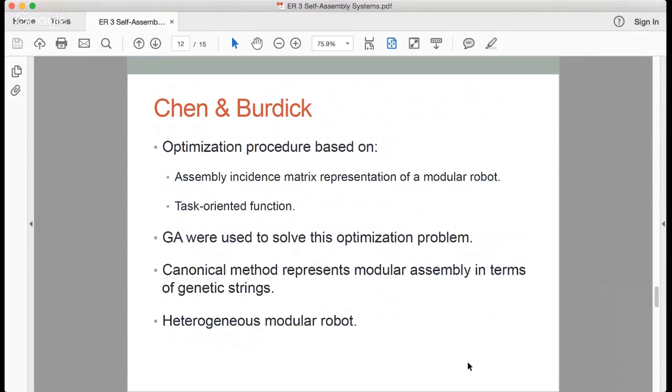Instead, a discrete combinatorial optimization algorithm, which employs the modular robot evaluation function, is a desirable alternative because it's cheaper. In short, the GA method is well suited for the modular robot problem, especially when using the method to effectively encode modular robot assembly configurations in the bit strings required for the GA procedure.